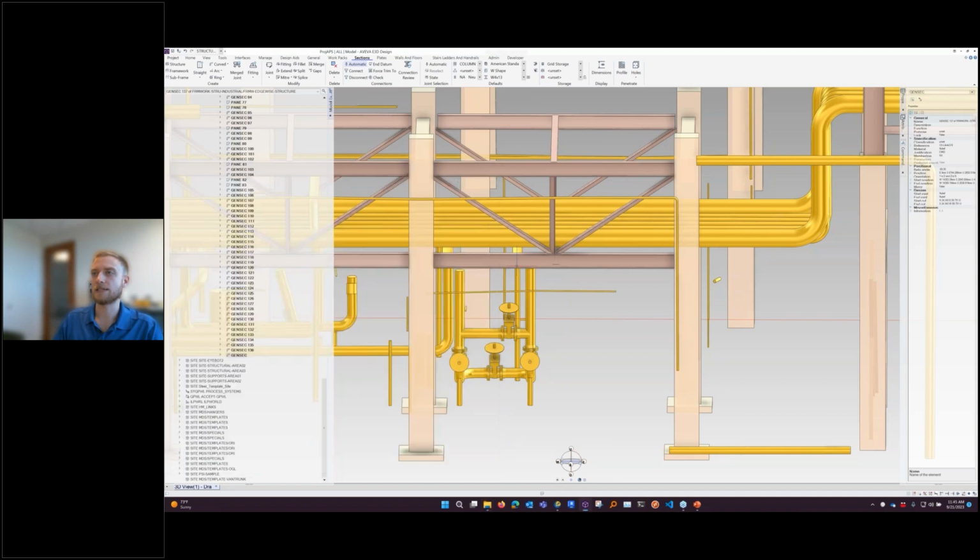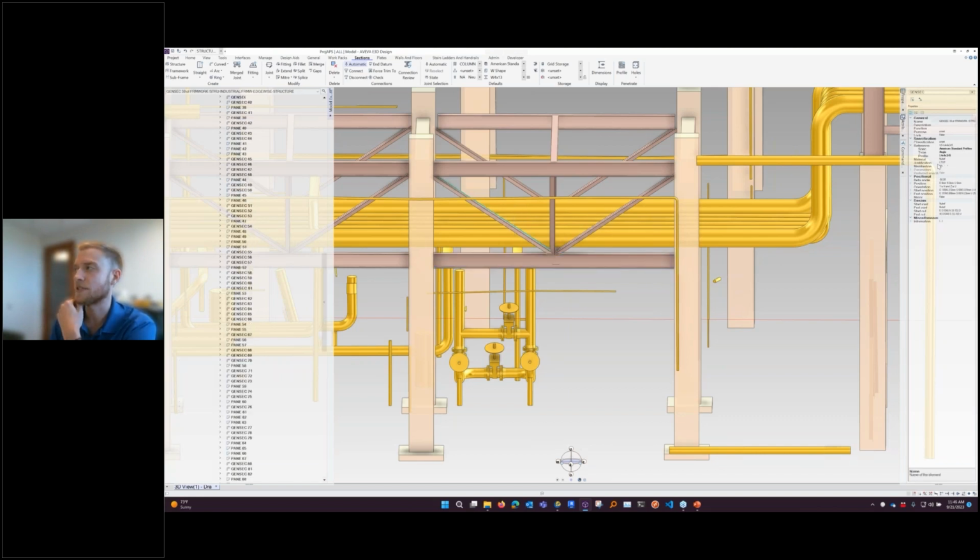So now I can click on this, and the properties are going to be based off of what we define inside of EdgeWise. The reference is the American standard for profiles. It's a W12 by 35. I can switch it out with any other steel because these are native components. We also have the justification defined correctly based on what it is. For angle iron, if it's a beam, it'll be left top. If it's a brace, it'll be center middle. We try to make that flexible, so that it aligns roughly with the things that we need it to.